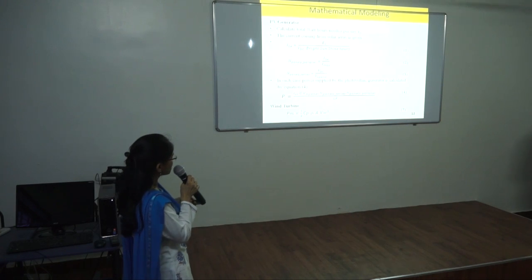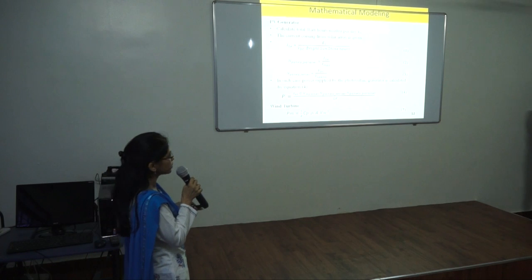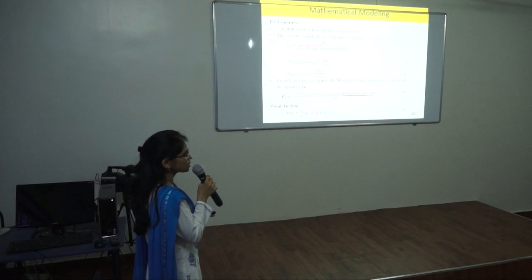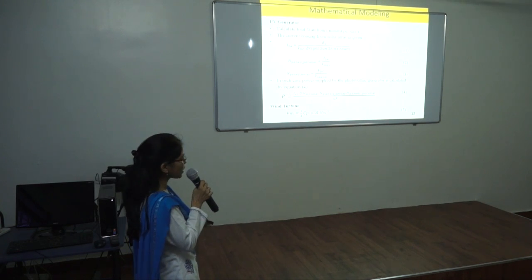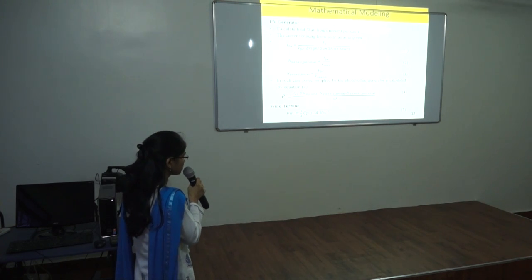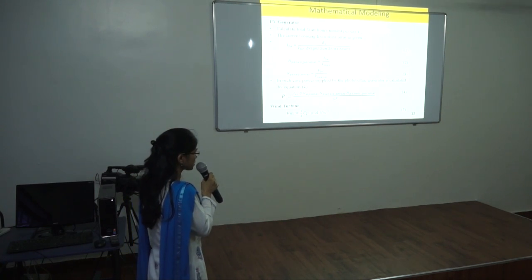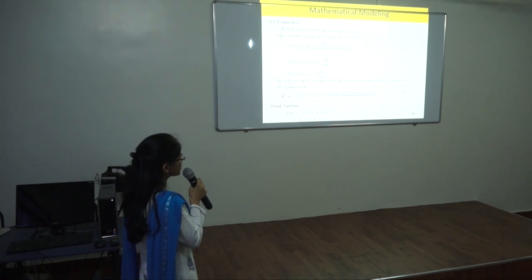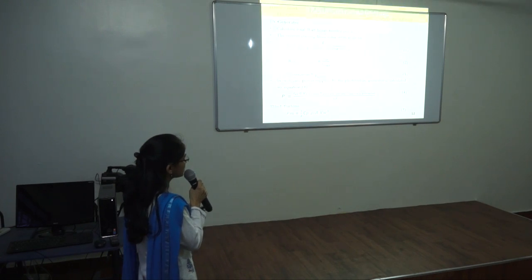So, for the first design, the PV generator, first of all calculate the total watt hours needed per day. After finding the total watt hours needed per day, find out the current coming from the solar array, which can be obtained by using equation number 1. Then calculate the number of panels in parallel as well as the number of panels in series. From these three equations, the power supplied by a photovoltaic generator is calculated by using equation number 4, and similarly equation number 5 can be used for the determination of power from the wind turbine.